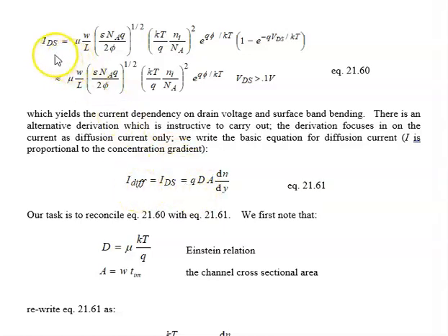This is diffusion current, kind of like a wolf in sheep's clothing. This is a situation where we're going to start with the basic equation for diffusion current as a concentration gradient. And we've seen this a number of times. We usually see it J diffusion without the A. Here we're going to include the A. D is the diffusion constant, and of course Q is just the electron charge, 1.6 times 10 to the minus 19 coulombs.